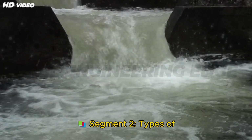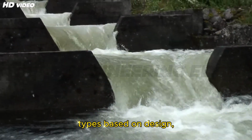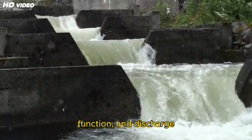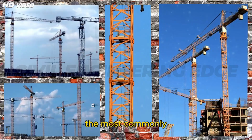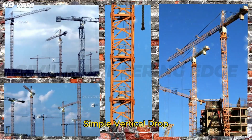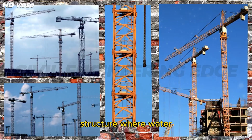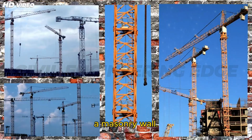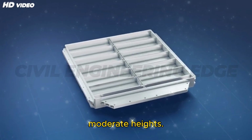Segment 2. Types of falls. Canal falls are classified into several types based on design, function, and discharge range. Let's briefly explore the most commonly used ones. 1. Simple vertical drop fall. A basic structure where water drops vertically over a masonry wall, suitable for low discharges and moderate heights.